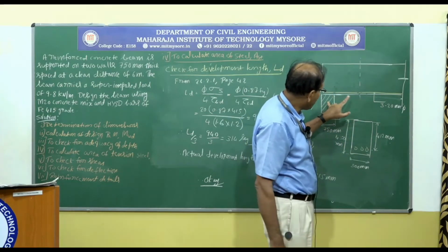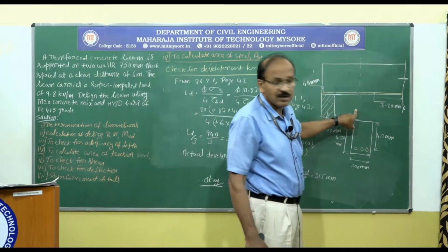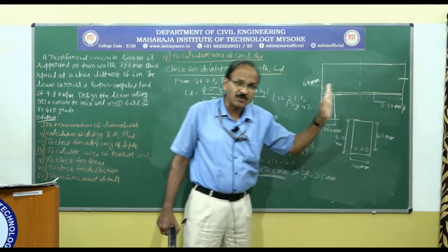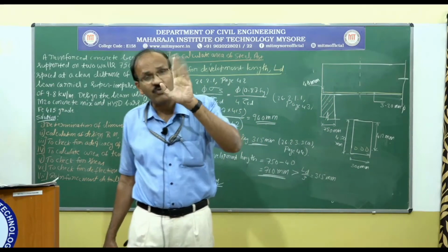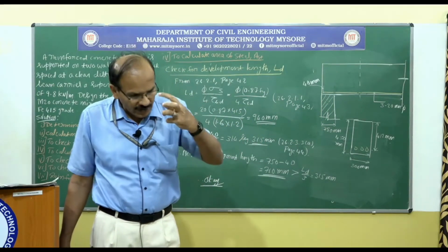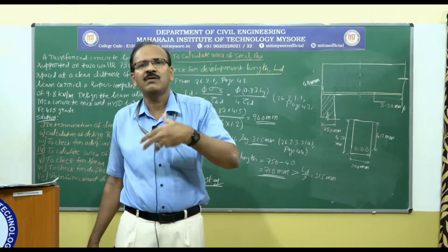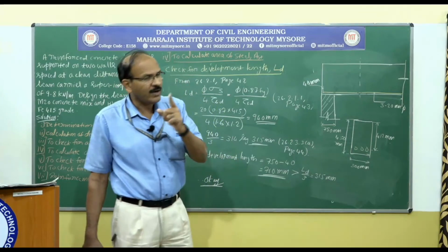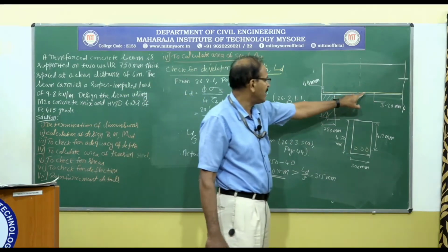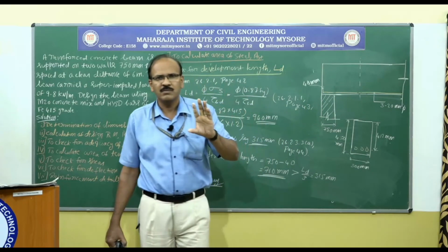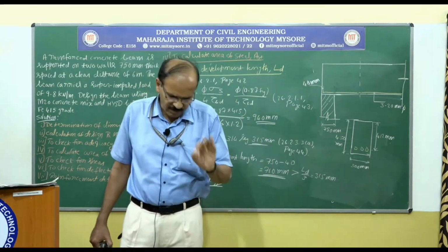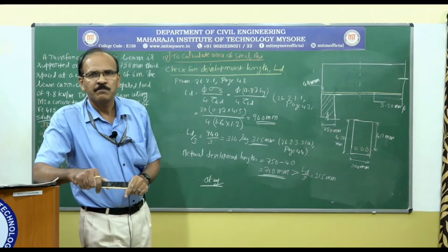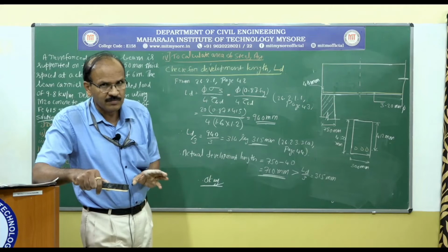Once you find out where you can cut that 1 bar, from there you extend that for a distance equal to 12 times the diameter of the bar or 1 effective depth. So this requires a little bit of calculation. By keeping that in mind, what I have done is I have ignored it, instead I have continued all the 3 bars into the support. So that way I am using a little bit of extra steel material. Is it clear to you?